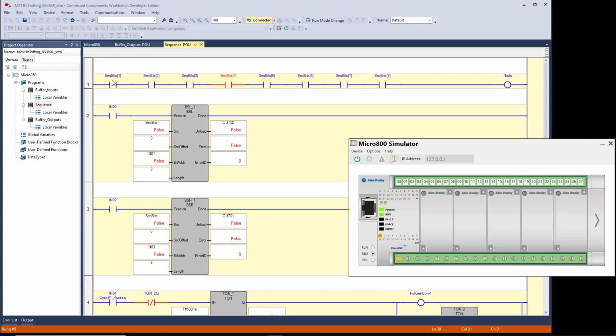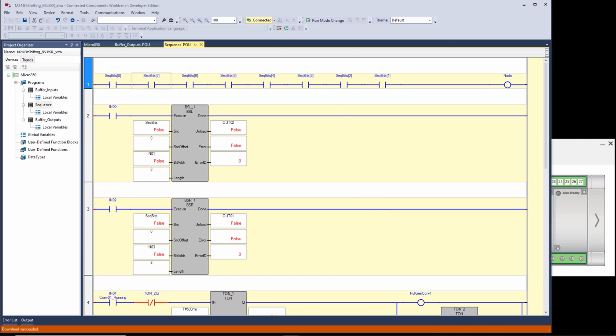So I'm going to pause and draw these different, and then I'll be right back. Notice what I did. I flipped the sequence of these around, so the least significant bit is on the right side and the most significant on the left side. And if you're looking at a word in memory, the least significant bit is normally drawn on the right side. So if you shift left, that means you're shifting from a lower significance to a higher significance.